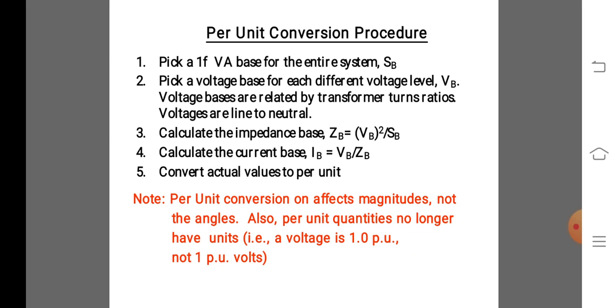It is the ratio of kilowatts generated to the product of plant capacity and the number of hours for which the plant was in operation. That load factor can be station output by plant capacity and hours of use.